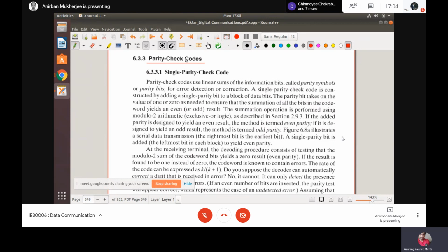also you have the received message bits. From this appended and received 3 bits, you will have an idea whether the message bits received are the original message bits or it has undergone certain error. It has suffered from some error, due to the channel. Please remember, due to channel noise or something.